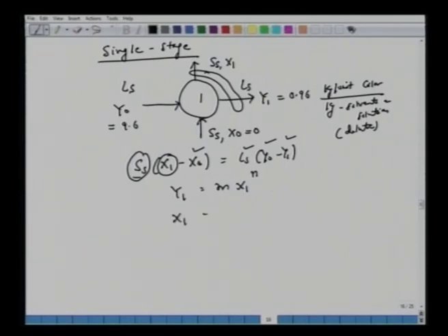So x1 equals y1, which is 0.96 over 8.9 times 10 to the power minus 5, to this power 1 over 1.66. So that's n, and if you do these calculations you will get 260 units. So again this is x1, this is your 260 of mass, this color adsorbed in this carbon solid phase.